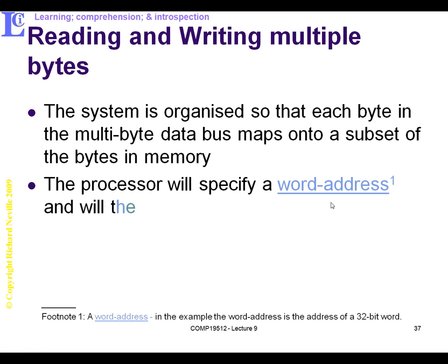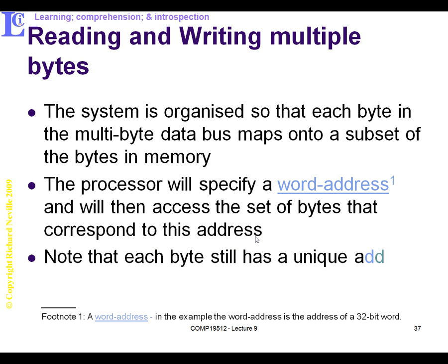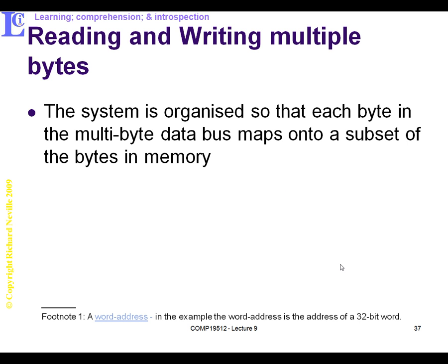Okay, so now the naming convention we're going to use is word addressable as opposed to byte, where word has to be specified in size. This is a 32-bit word addressable memory, and it's a set of 4 bytes corresponding to 4 different addresses. So each of the 4 different addresses, the 4 bytes, has a separate or unique address. Let's go and look at that.